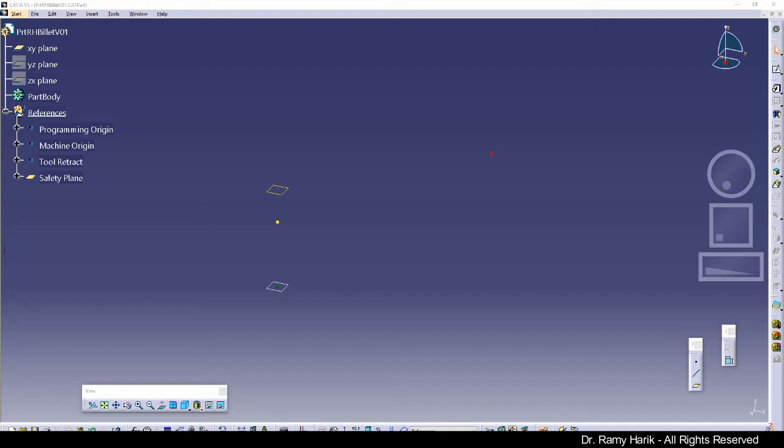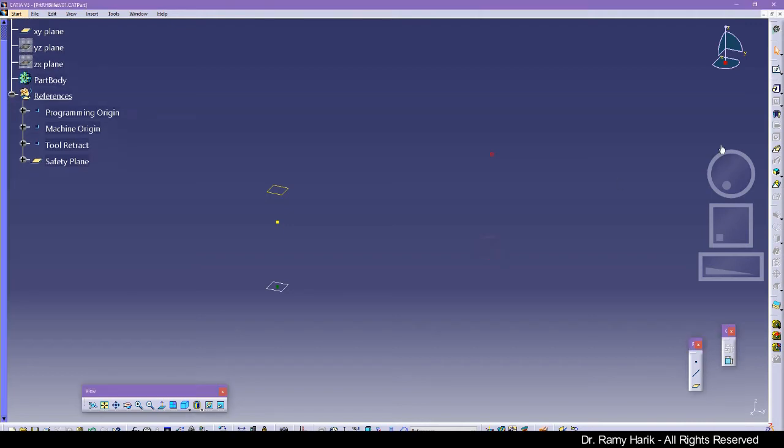Let's go ahead and start creating the billet and the part creation. So the dimensions that we're looking at is a centered rectangle of, it looks like, 4 inches. Let's verify that. So we have XY plane for 4 inches, and then it is extruded 2 inches, obviously in the negative orientation. All right, so that's fairly simple.